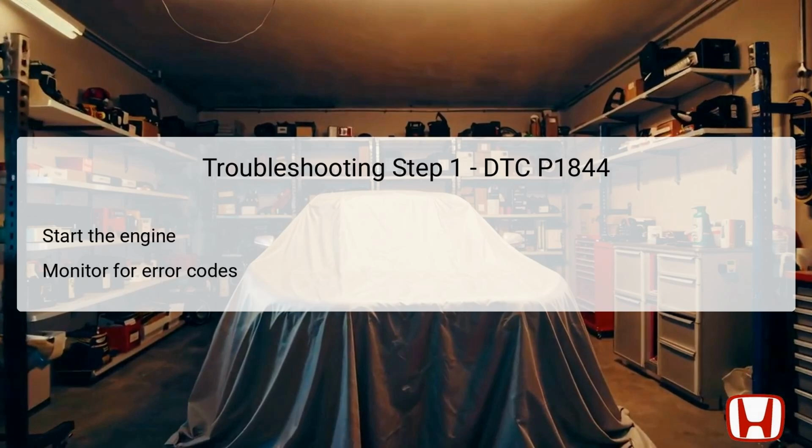You'll want to utilize an appropriate scan tool to communicate with the TCM, allowing you to view any stored or pending error codes that could provide further insight into ongoing issues. As a standard diagnostic practice, ensure that the engine is at a stable operating temperature to capture accurate data and responses from the vehicle systems.